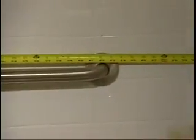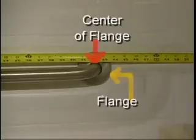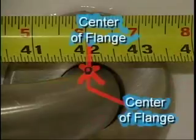Many times while measuring the grab bars, the survey team has found that contractors install the grab bars incorrectly because they are measuring from either end of the flange, not from the center of the flange.